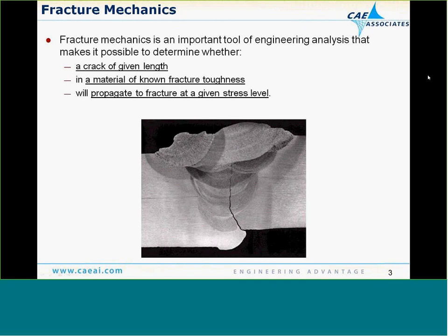And then at that point, using safety factors and so on, you can set inspection intervals to say, okay, you can turn these other ones back on, you can run for another 10 months, and then we recommend you inspect again, and then you redo the analyses and so on. And that's kind of the idea of how fracture mechanics would get used.